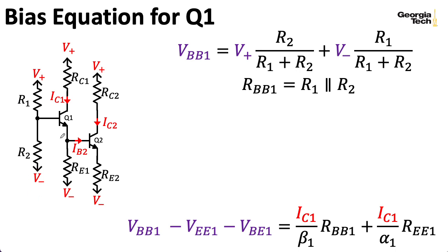Now we need to think about the Thevenin equivalent looking out of the emitter. And now this is a lot more complicated than what we had in the previous lecture. And again, we imagine that we're cutting the line here. We can imagine that we're under the influence of 2 sources.